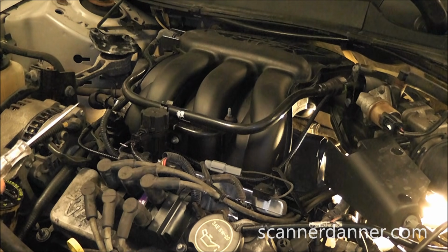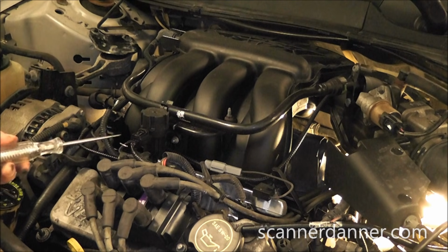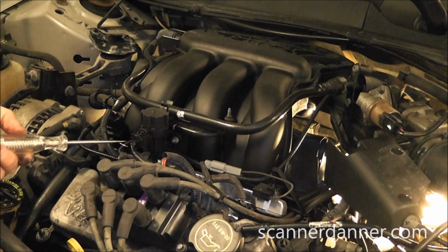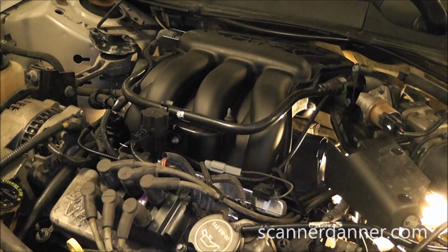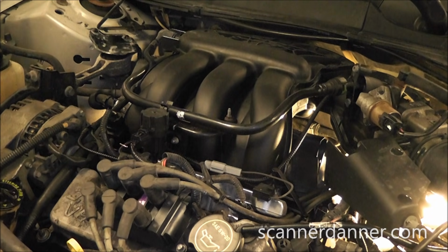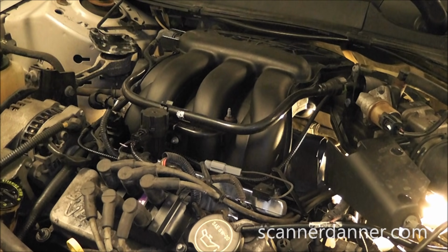Got my test light connected to ground, and I'm going to touch on the EGR control wire. So you heard the idle get real rough. That's great. And generally what you want is that car to just about stall. Now I just did that test when we first started the car, so we'll let it stabilize. We'll redo the test one more time once the idle comes out a little bit more.